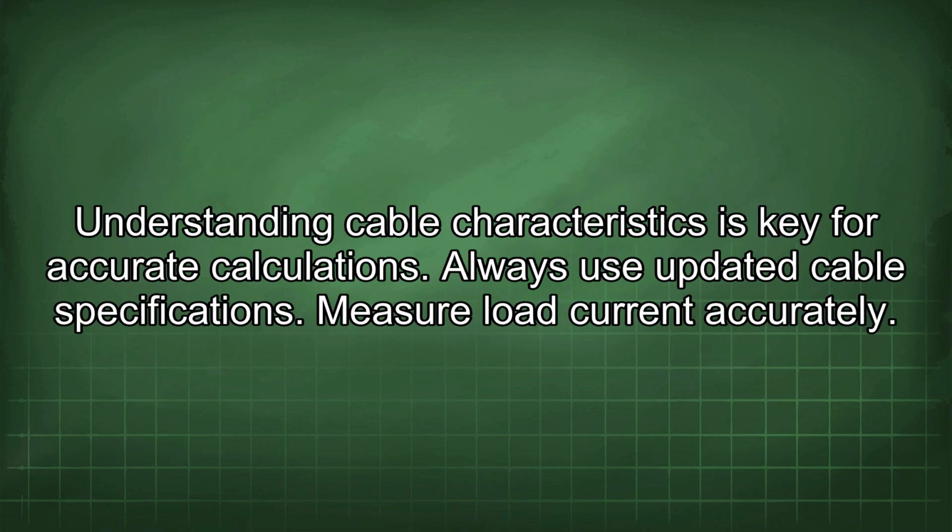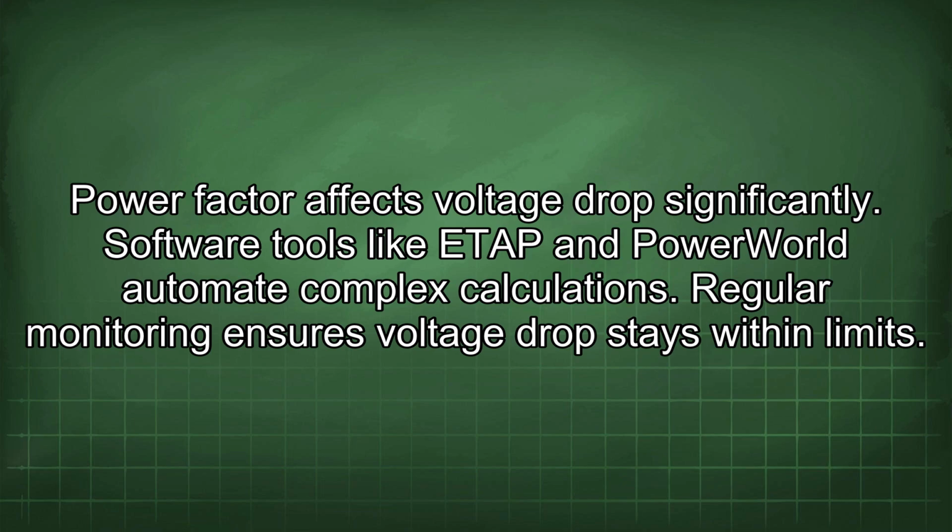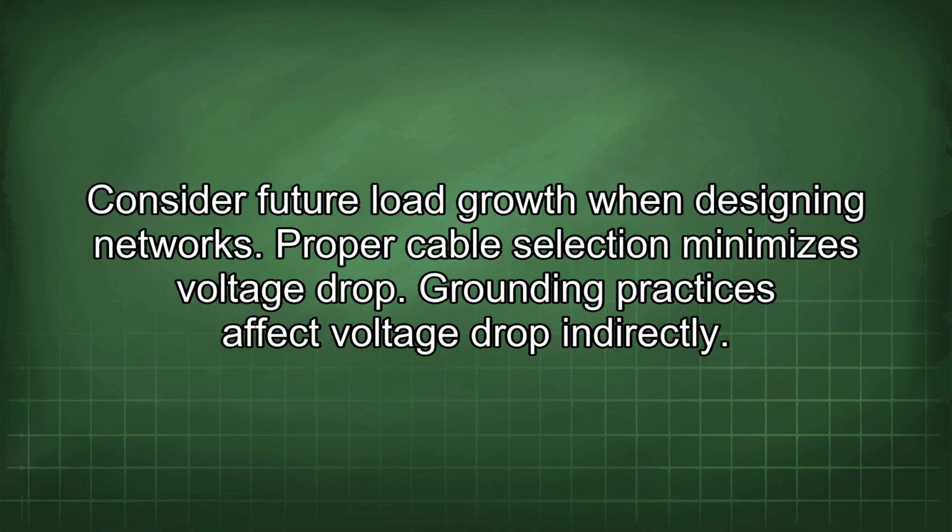Understanding cable characteristics is key for accurate calculations. Always use updated cable specifications. Measure load current accurately. Power factor affects voltage drop significantly. Software tools like ETAP and PowerWorld automate complex calculations. Regular monitoring ensures voltage drop stays within limits. Consider future load growth when designing networks.